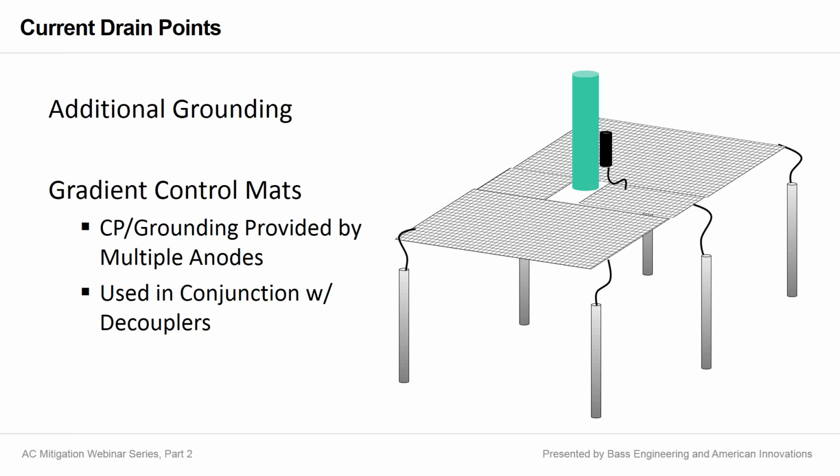We would typically recommend a number 6 cable with an HMWPE insulation. So it would not be your standard number 12 THHN lead wire insulation that you might be accustomed to seeing on your magnesium anodes.